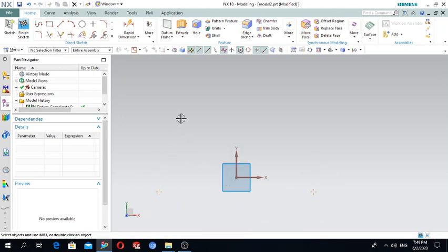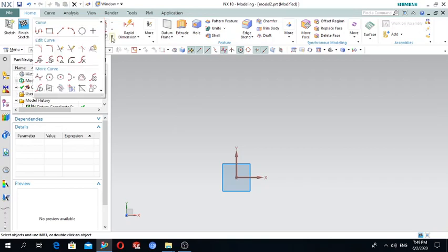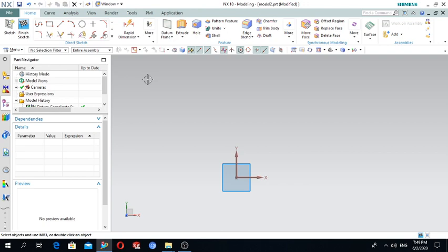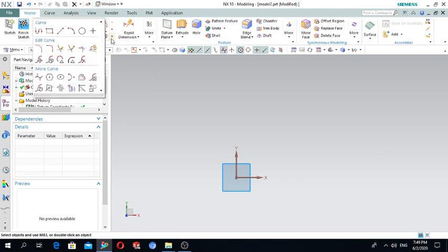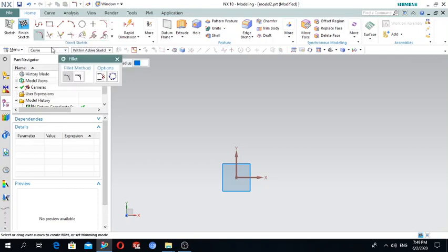Next, if you open the draw commands as we learned in the first lesson, we left some functions here. We will see this function today. The first function we will learn from this bar is make fillet. This command rounds a sharp corner created by the intersection of two lines, arcs, circles, and rectangles, or polygon vertices. To activate this, press this one.